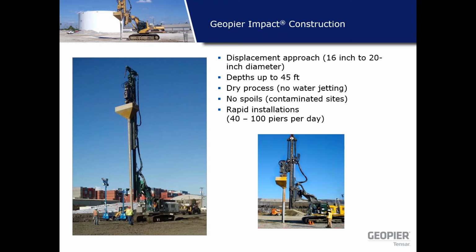It's a rapid installation technique. We can install about 40 to 100 piers a day. The diameter of these elements varies from 16-inch to 20-inch, and the depth limitation is about 45 feet.